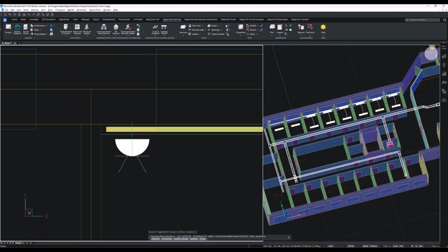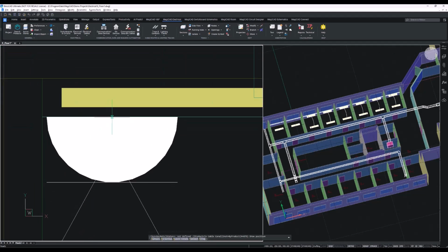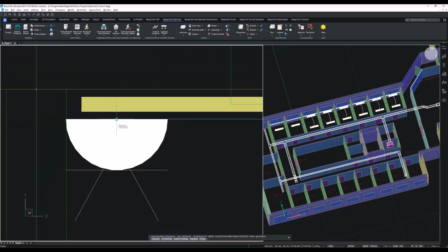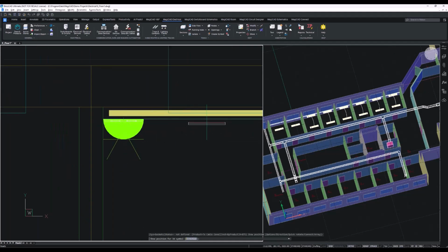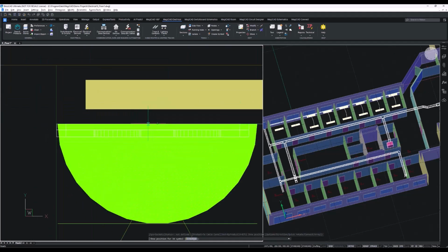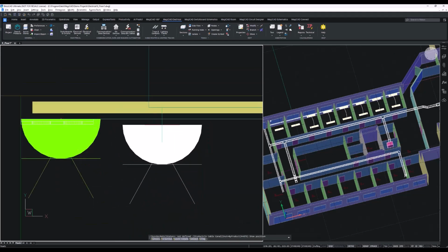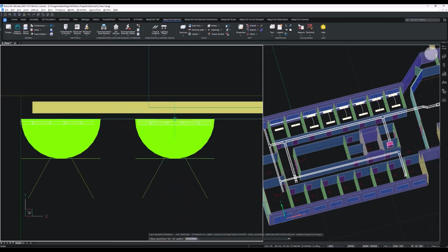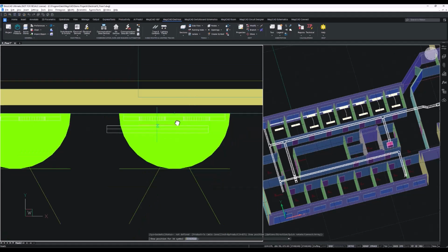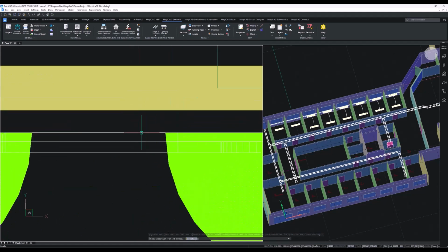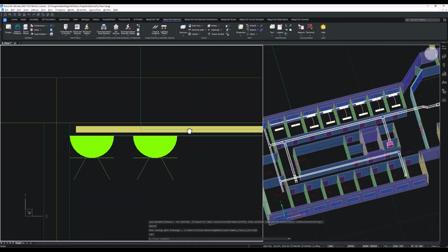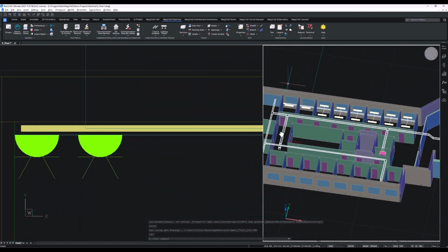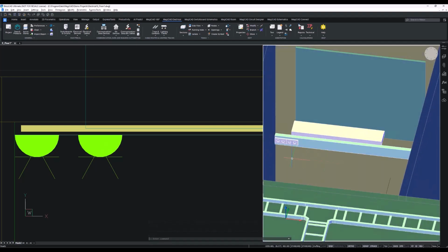And here I'm going to present this option that we ticked. First of all, MagiCAD suggests us to install the 2D symbol and only then the 3D model separately. Then let's install the second socket. I will place the symbol here, but the physical model here. And let's see how it looks like on the 3D view.